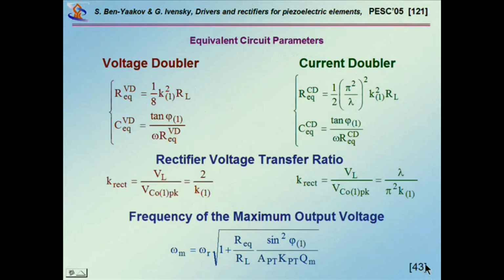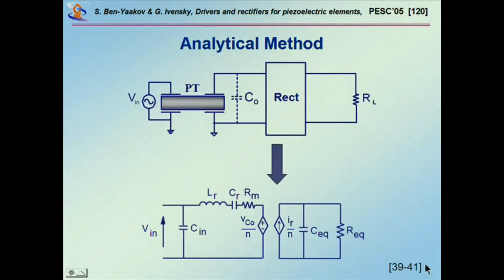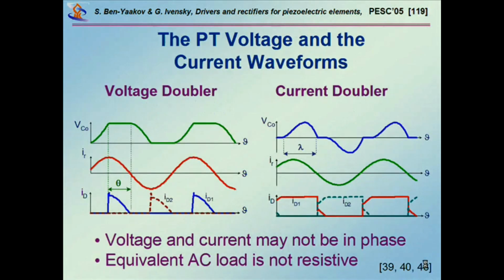Yes? This only accounts for the first harmonic or RMS? Well, no, it is assuming first harmonic only for this inductor current. But you see, real power is coming only from the first harmonic of this current.